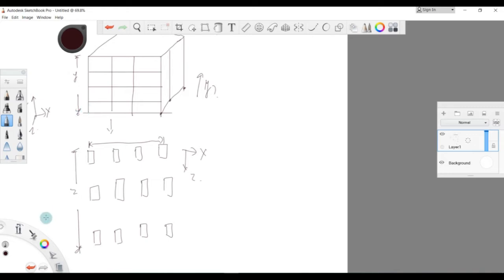Okay, and number of bays means how many bays you want. This is one bay, this is another bay, this is another bay. So we got 3 bays here in the X direction, and here also in the Z direction, how many bays we got? We got 1, 2 bays. And in the Y direction, how many bays we got? We got 1, 2, 3 and 4 bays. So in this way, however your structure is and however you want to define your structure, you can define the bays.